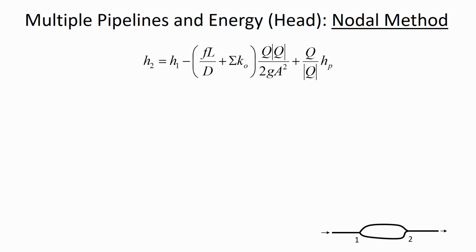Because sometimes we say Q times the absolute value of Q, because sometimes Q has directionality, like a negative, and we want to preserve that negative sign in the Q. If we had just squared it, then that negative value would have gone away. But if we preserve the directionality, by doing Q times the absolute value of Q, that would help us correct when we've made some bad assumption about the direction of flow. That'll come up later on, not immediately, but I'm glad you asked that question.